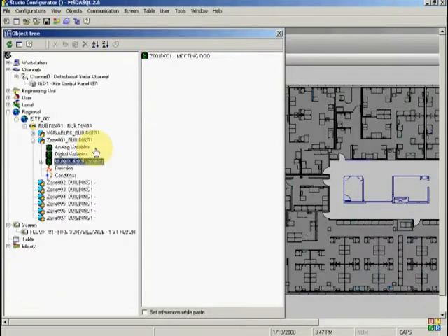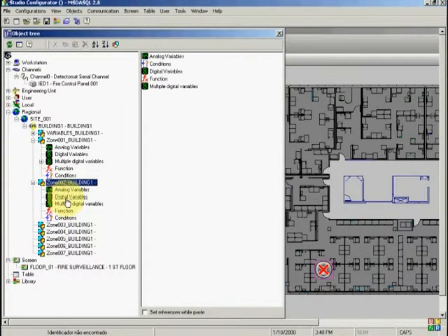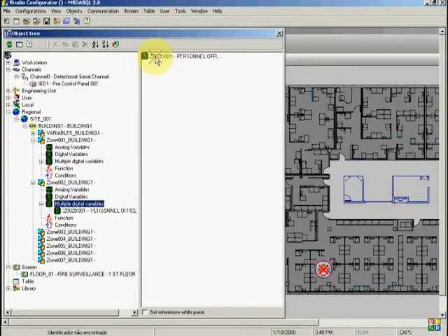The DB Creator associates each Detectomat module and panel element with an existing visual object library. So to include these modules on a new screen, just define their basic position on the screen, select them all and select Create Visualization.